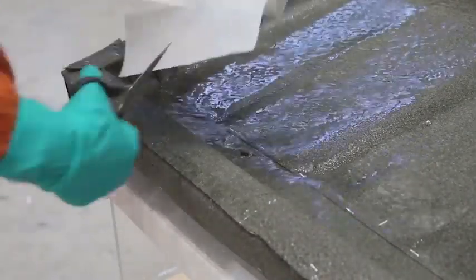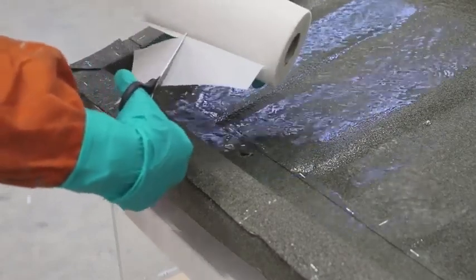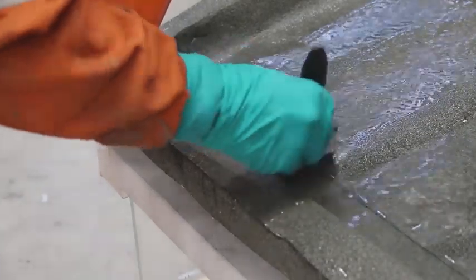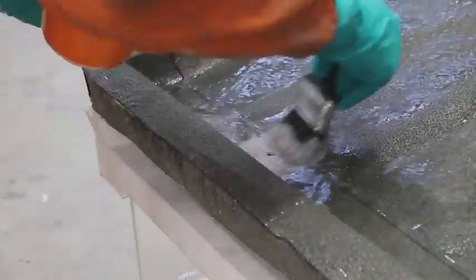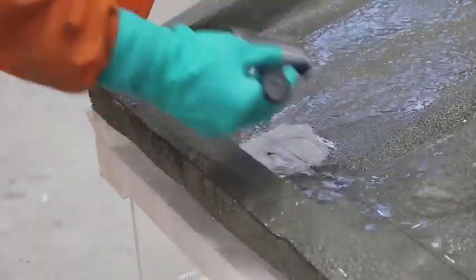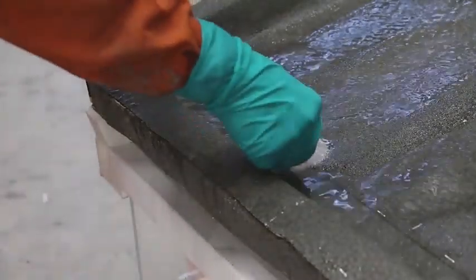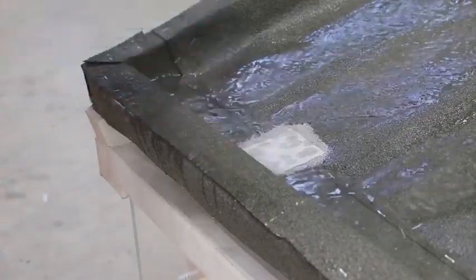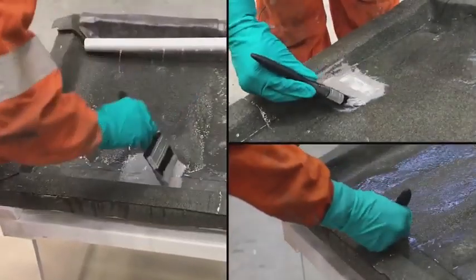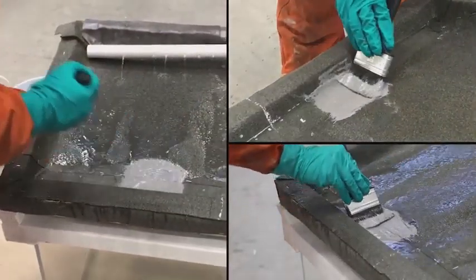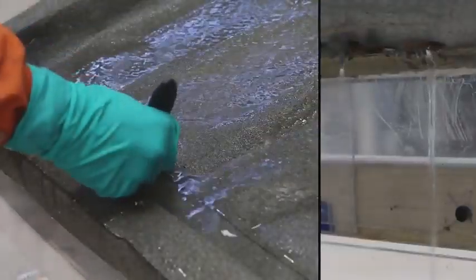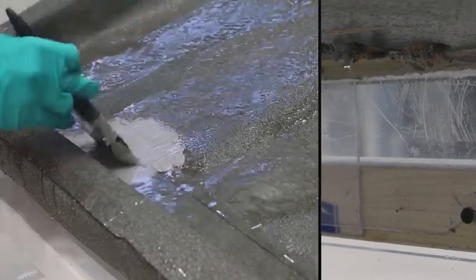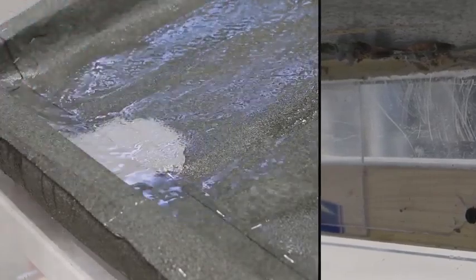The great advantage for this material is that it can be applied even during adverse weather conditions, with no need for conditioning or primers. The material adheres strongly to all common roof surfaces, such as felt, asphalt, lead, glass, concrete or brick, and will cure at low temperatures. The reinforcement sheet within the material allows it to adapt to any roof movement. As you can see, as soon as the material is applied, the leak stops and becomes water resistant.